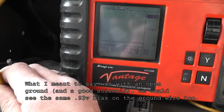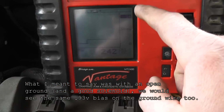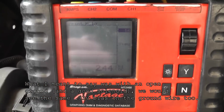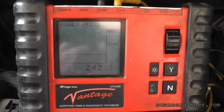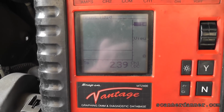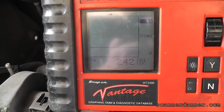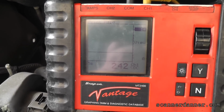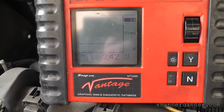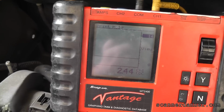I don't like this 2.4. You saw it went up to 12 when I commanded it. It was not pulse width modulated. This is probably logic in the computer for this trouble code. What I'm going to do is clear this code out of here and see if this changes things a little bit. Codes are cleared. Yeah, it almost seems like the computer's checking the circuit.